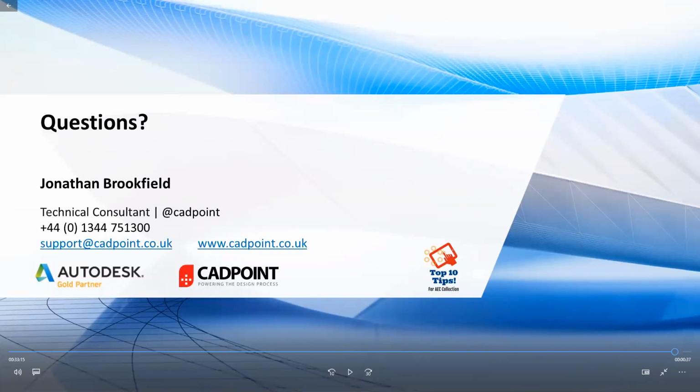Just to finish off, we've got a few last questions. Can Entourage be added to the base InfraWorks model without adding additional roads like cars and street furniture? Oh yes, it most certainly can. When I was discussing in the webinar the difference between a component road and a planning road, by default all the roads created in InfraWorks are planning roads, which is just a simplistic road along an alignment that follows the topography. But you can easily change the aesthetics to a motorway or a road with pavements, etc.